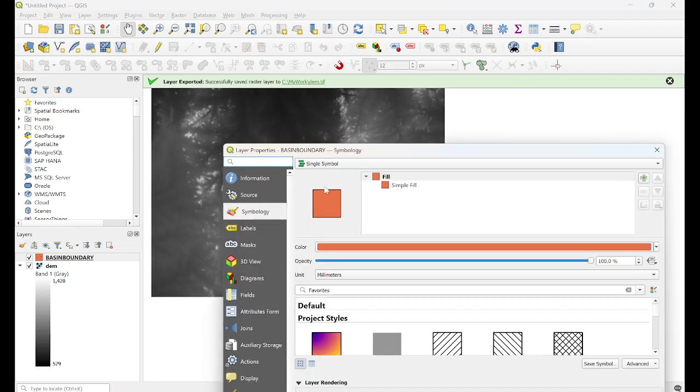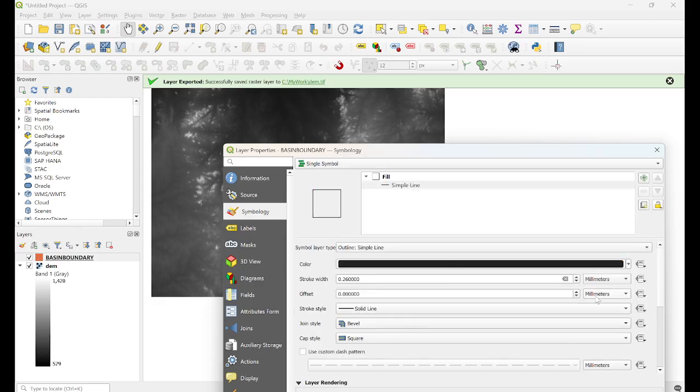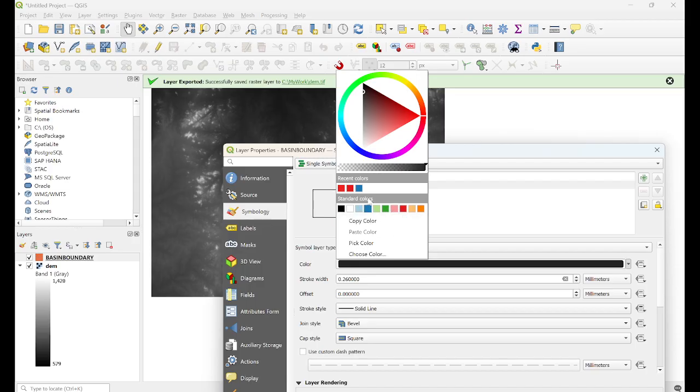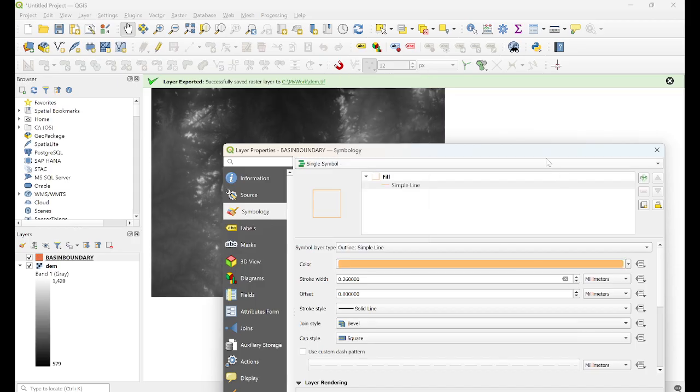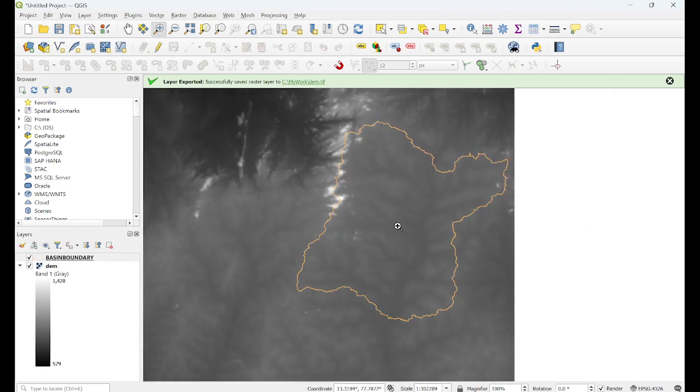So now you can do all the analysis and visualization. I put a yellow line here, right? So this is your catchment area, and you can clip this particular catchment area and do a lot of analysis. You can clip the land use file out of it, and you can do hydrometeorological data analysis for this one.